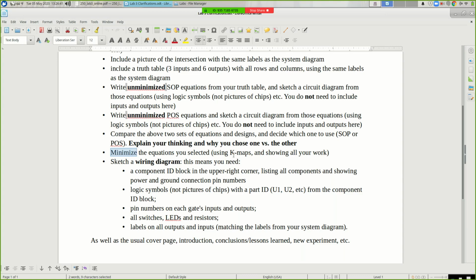And so you only really need to minimize 3 equations, for your west, east, and south green lights, and then make the reds the complement. Or if you do a product of sums, maybe you'll write equations for the red lights and then make the greens the complements of those. It's totally up to you, okay? This is a very creative, very designy part of the process.